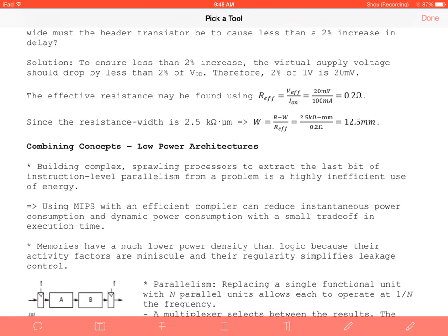In MIPS, there are 5 stages, so we have instruction fetch on one instruction while we're loading data memory on the instruction that's 5 before, right? This becomes inefficient if you keep trying to cut it down into different stages. 5 stages is typically the most efficient from a power consumption standpoint. This is why MIPS was chosen that way. However, if you start adding 20, adding 30, it becomes more inefficient. So this is where parallelism comes into play.